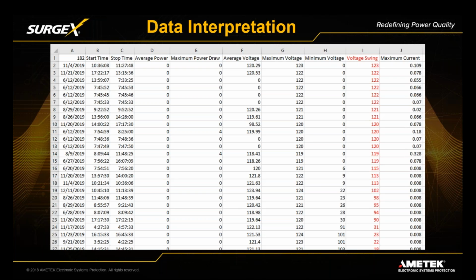Vince, if I can just chime in on that, the way that we determine all of this within that 30-minute window is we have new measurements every 3 AC cycles. So that's basically our RMS calculation window: 3 AC cycles. With every 3 cycles, we get the new measurements, and then we ask, is this measurement greater than the previous maximum or smaller than the previous minimum, and then update those registers. We also add to our accumulator to do the average measurement. So we're looking at these values really frequently and updating them, and then we just log them every 30 minutes, like Vince said.